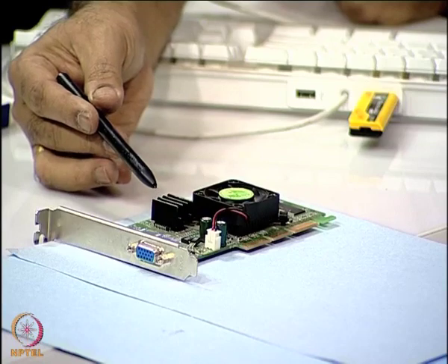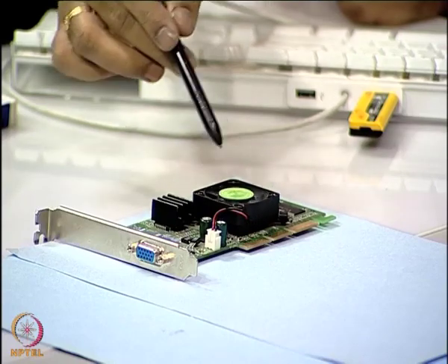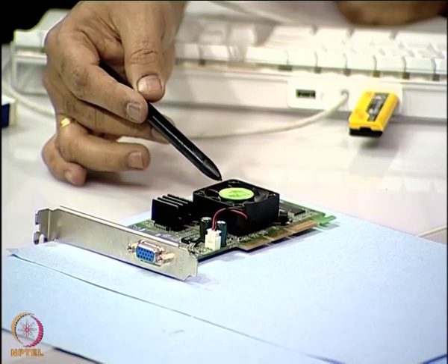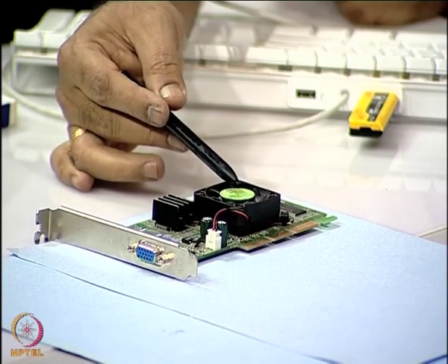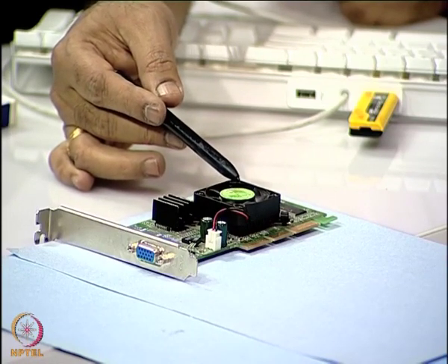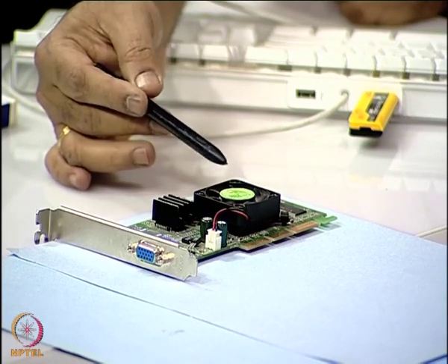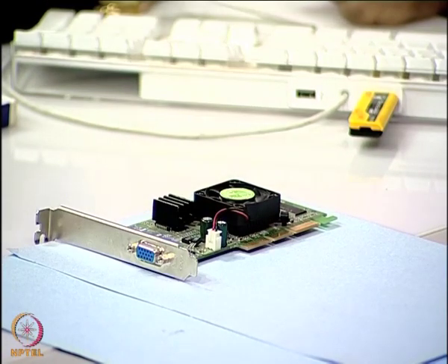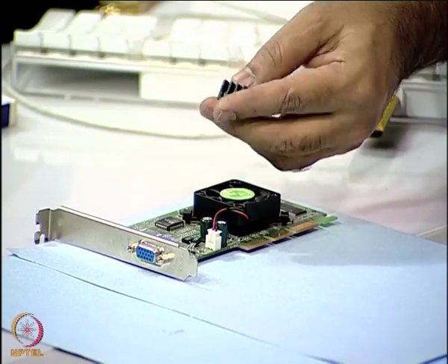In other cases, you can also use a fan. You can see here in this case, a fan is used on top of an integrated circuit. Obviously, this material is lightweight, but it is positioned in such a way that it is mounted on top of the active device to remove heat. So, in your thermal analysis, you will have to carefully look at whether you require a heat sink or a forced cooling method like a fan, or you do not require these at all if it is not a major problem. So, this material of heat sink is an aluminum material,